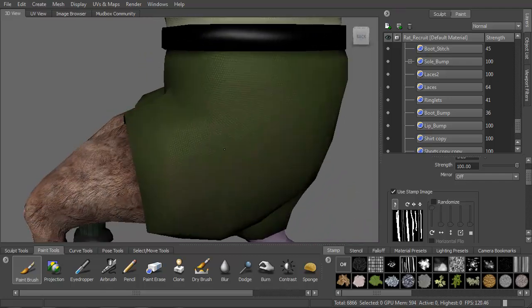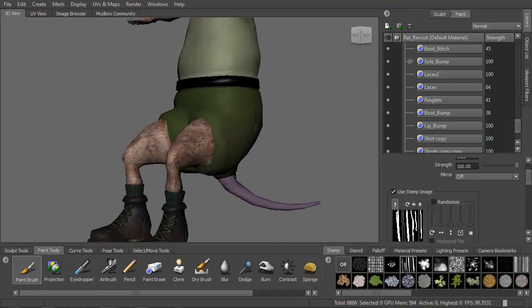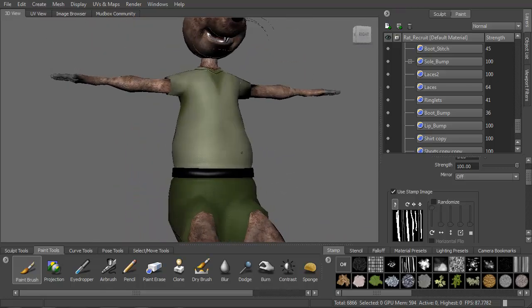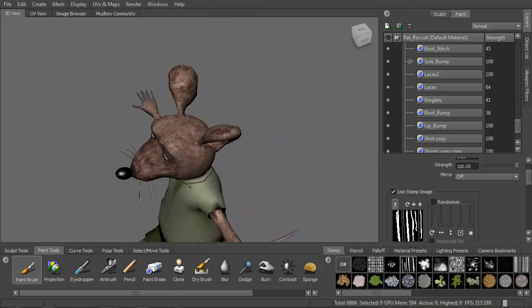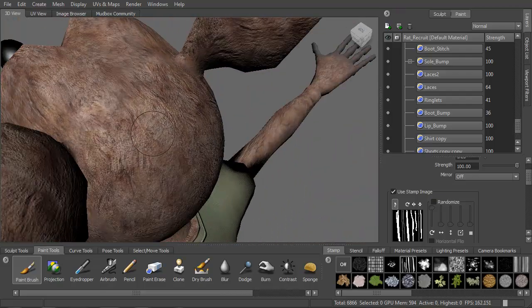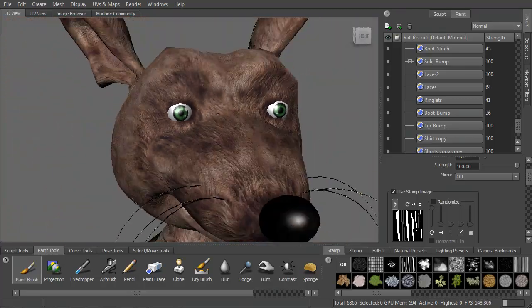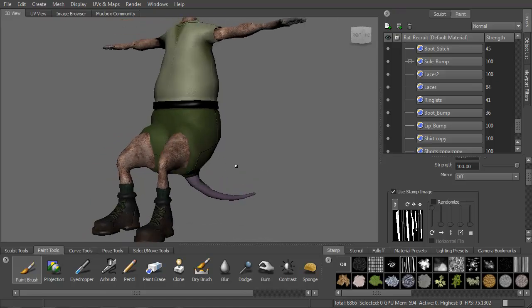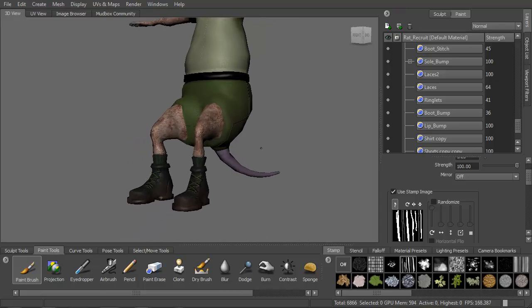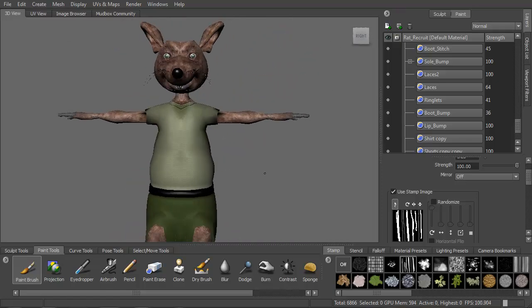Because I put my specular in my alpha channel, I'm just using the values. I'm only controlling its strength. I'm not controlling its color. If you need to control its color, then you would actually keep your specular maps colored, and you would have to, in that case, export out a different set of textures that are colored, because you can't have color in just one channel. It's just a grayscale image.